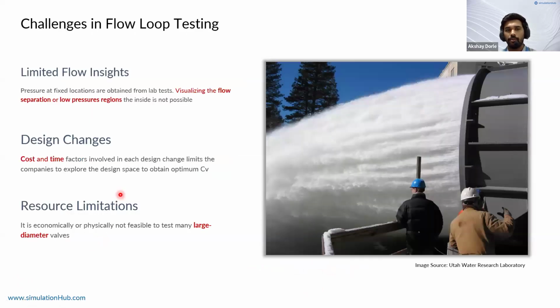So the challenges of flow loop tests: it's limiting in valve insights. You can get the FL value, but it won't give you any insights because you cannot visualize the flow inside a valve in these tests. It costs a lot of time, so there could be a waiting time for physical flow loop tests in laboratories, and there's a lot of cost involved. There's a lot of time involved, and